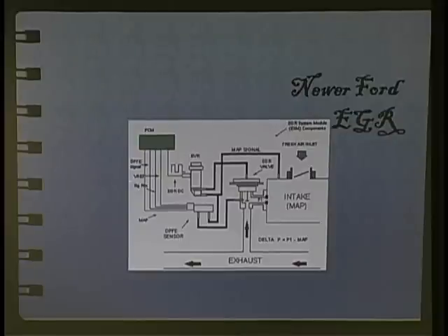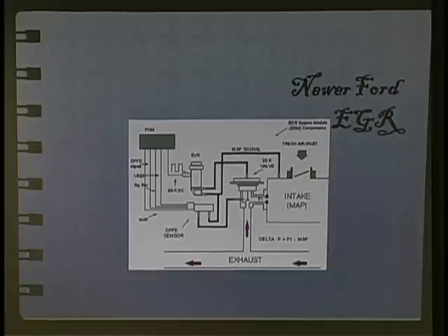Now, you do know that Ford stopped putting their hoses down on that tube. That tube's gone. So they put one at the base of the EGR. Now the orifice is where the EGR connects to the intake, and the other one goes up to the intake manifold. I don't know if you've noticed, but on newer Fords, the last three years, there's a PID called MAP. It's back. That is MAP, manifold absolute pressure. So it's the same system with a DPFE that never goes bad.